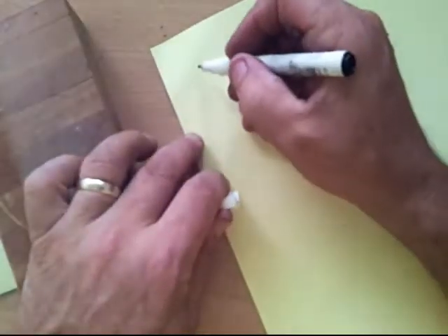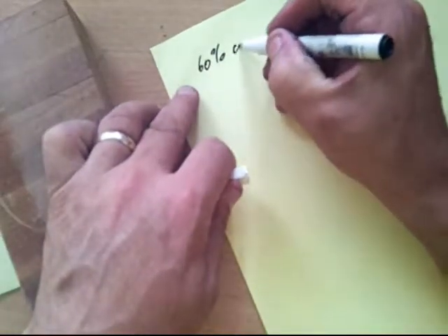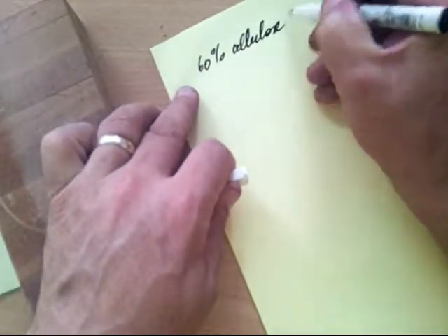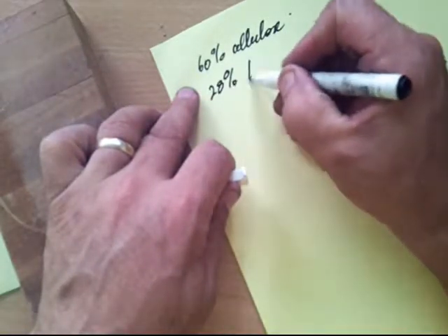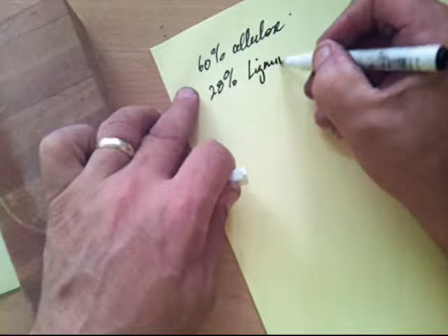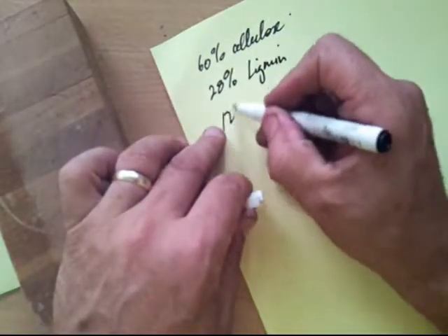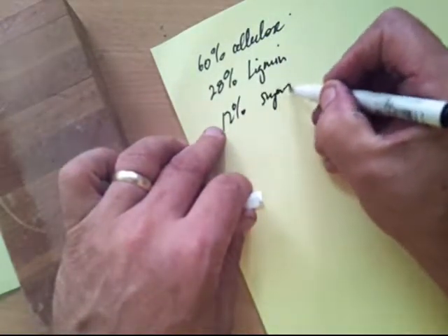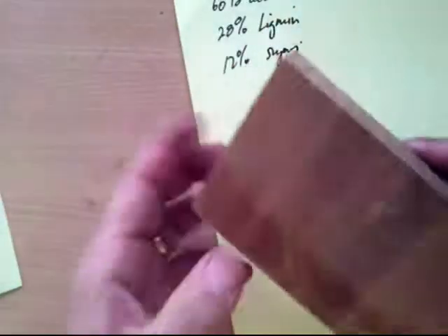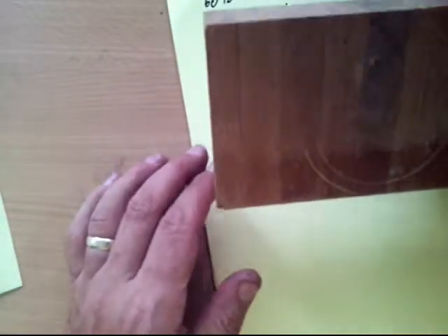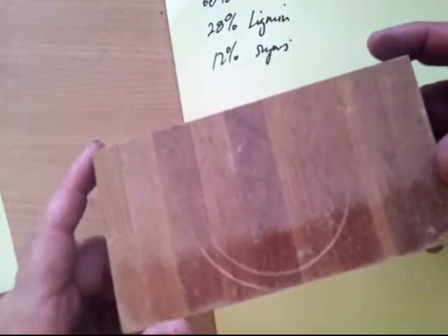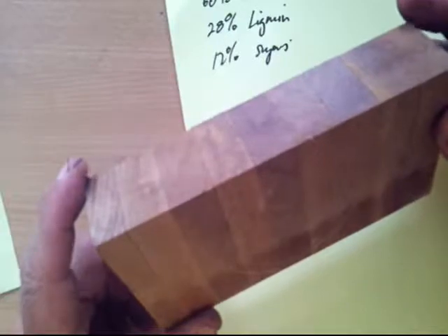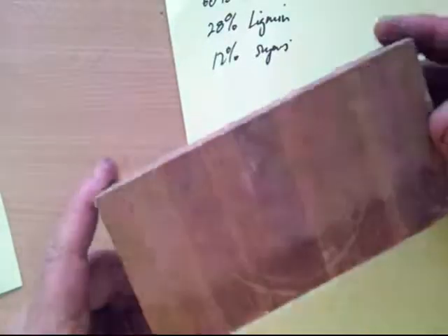We spoke about the old bows and how they were used. And wood is made up of 60% cellulose, 28% lignin, which is a kind of glue, a natural glue, and 12% sugars. So that's its composition. It's easy to work, it's easy to join, it's got a very high strength to weight ratio, higher than steel, and has a relatively high stiffness.